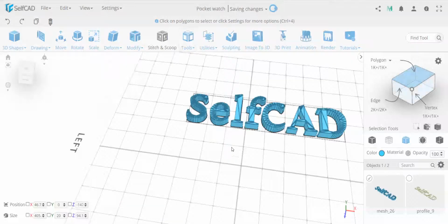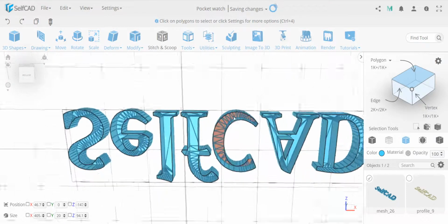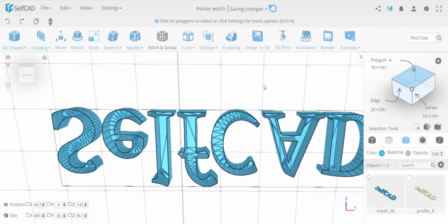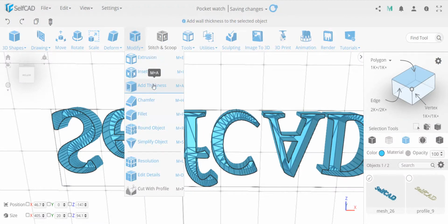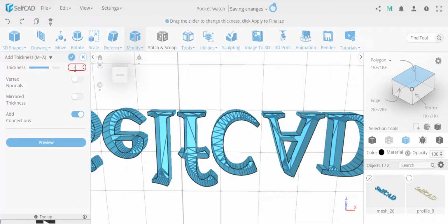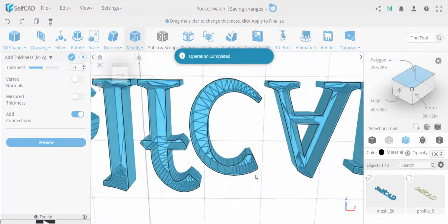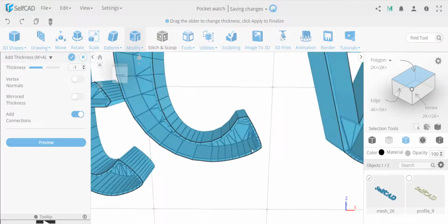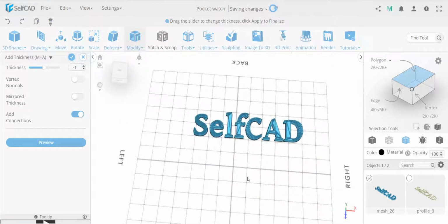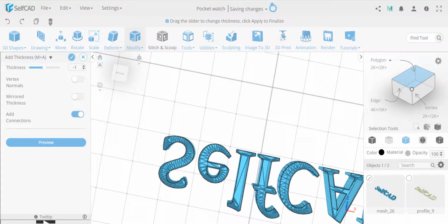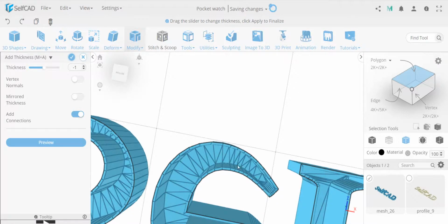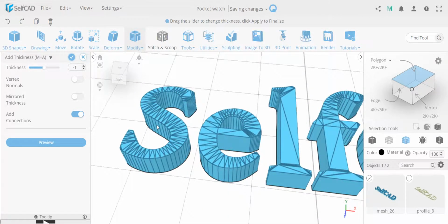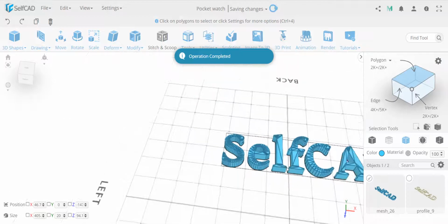The reason you would use extrusion sometimes for this, I'll show you other advanced use cases soon, but one of the ideas is if you want to keep this open, just add thickness to it. So you can add thickness to it, and let's say I make it -1. In this case, you can see this becomes a manifold mesh where it has some wall thickness, and this is kind of a hollowed text. And if you want to 3D print, say for example on filament, this may be a good solution for you to print something like this. So this is basically the basic use cases.